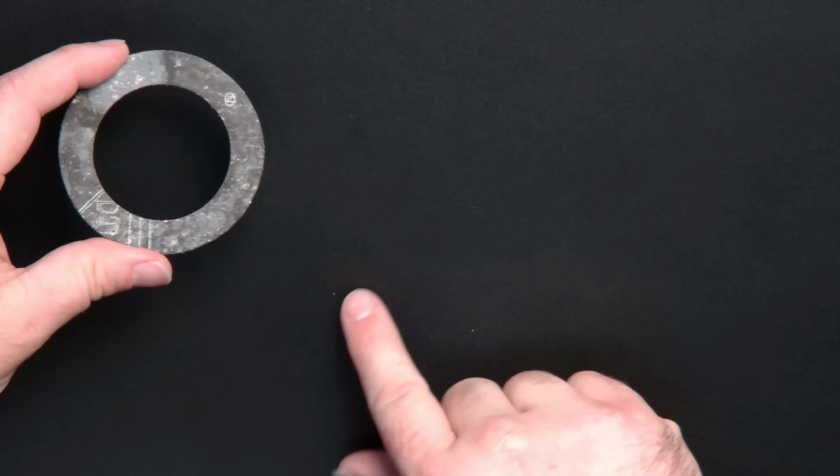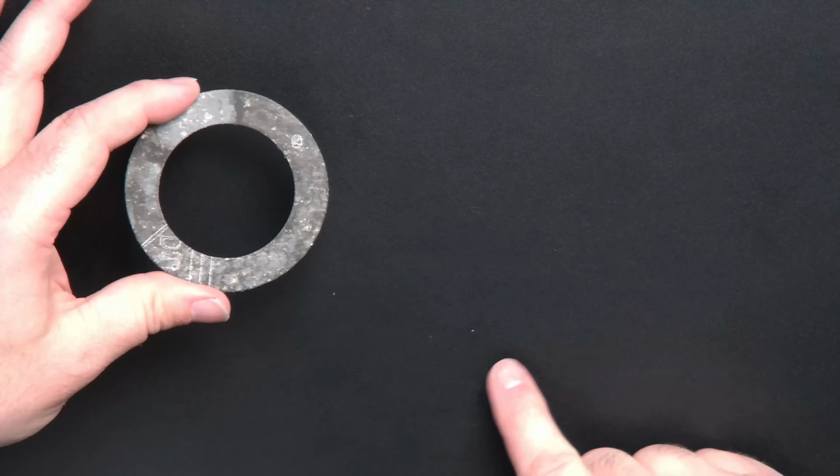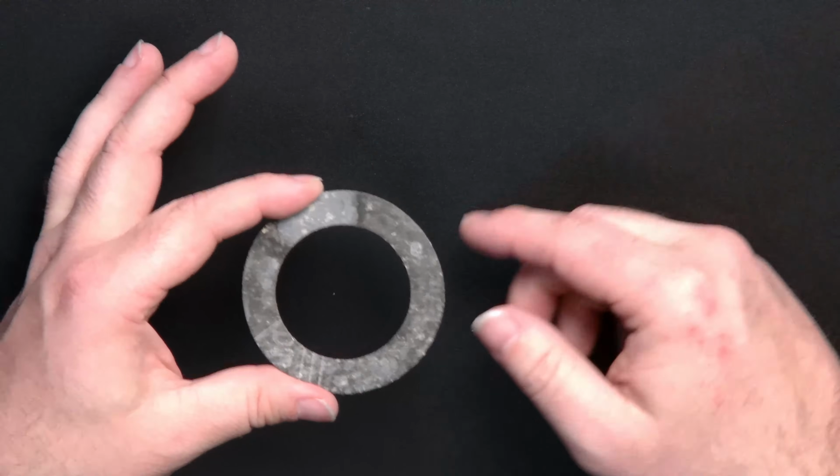And you can see here a little bit fell here, and here, we're going to get that all cleaned up. We have a HEPA vacuum and we take all the proper precautions. But I want people to see what an asbestos gasket looks like. So if you come across one ever, do not use a wire brush or wheel or grinder or anything like that, because that's what will make the clouds of dust that really truly would be dangerous. So this is an asbestos gasket like we saw advertised.